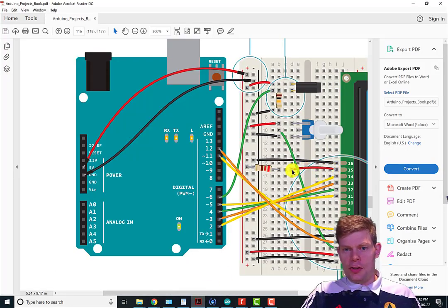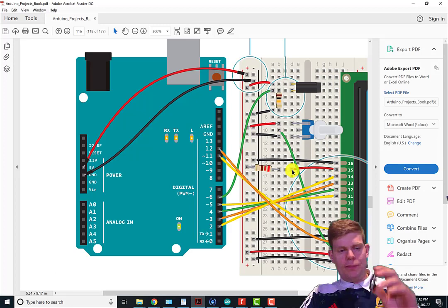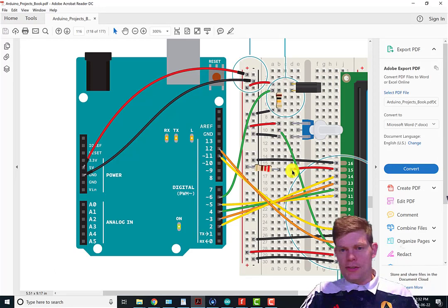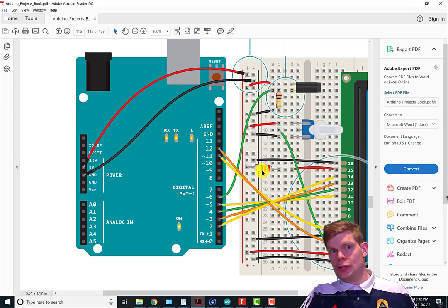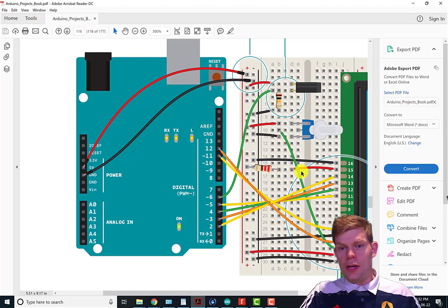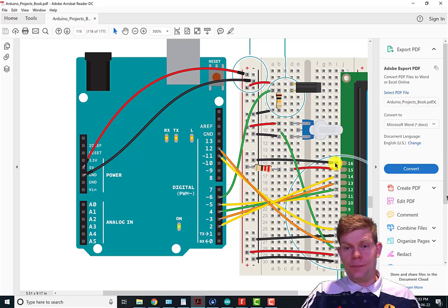So this thing right here, it's abbreviated as A. It's our anode, it's our positive backlight connection. And notice we are connecting it to our 5-volt rail through a 220 ohm resistor so we don't burn it out, just like we're used to doing with normal LEDs. And then this guy right here, that's your cathode. It's abbreviated as K on here. It's the last one. And that's the negative or ground connection for your LED. And we're just going to connect that straight to ground.